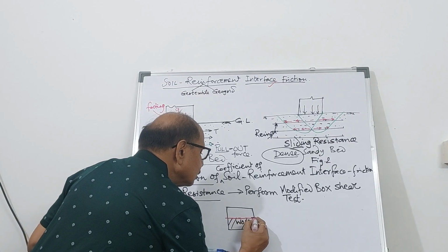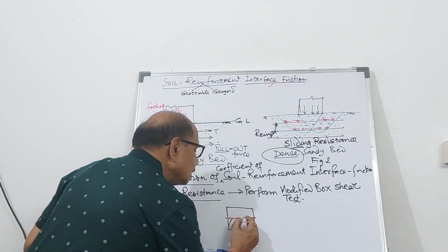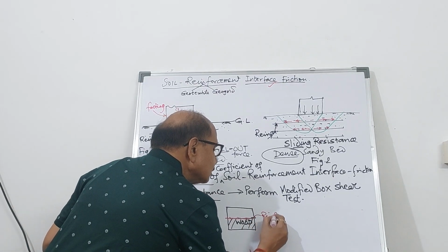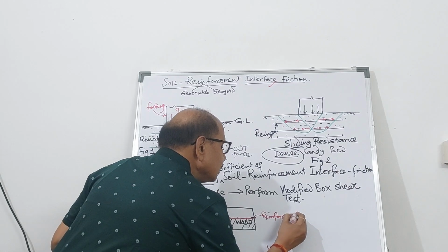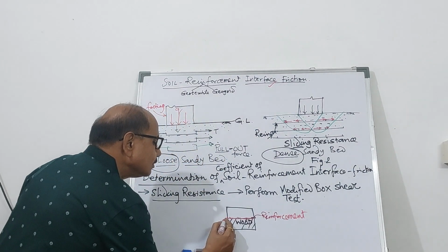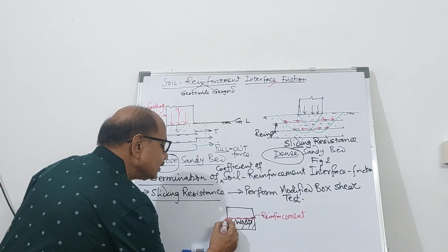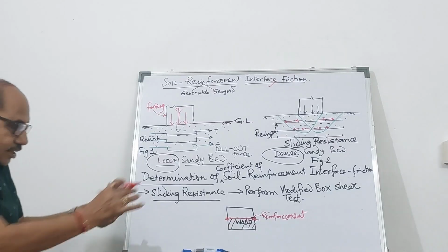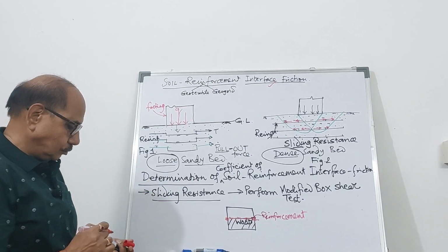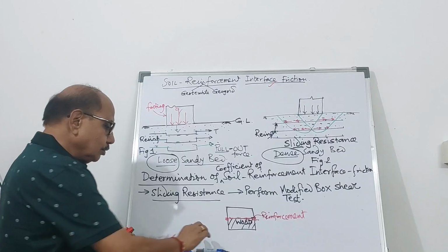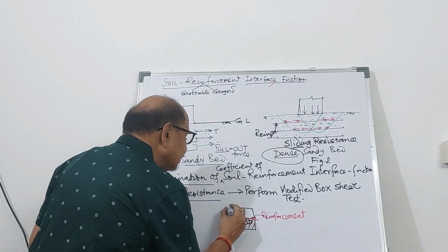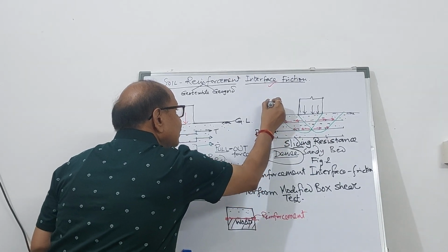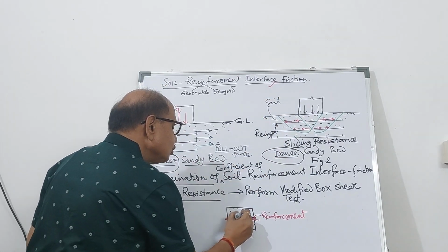This is the reinforcement, geosynthetic. You fix it here, so it is completely in position. And the top is going to be filled with the same soil. Whatever soil you have here, the same soil.